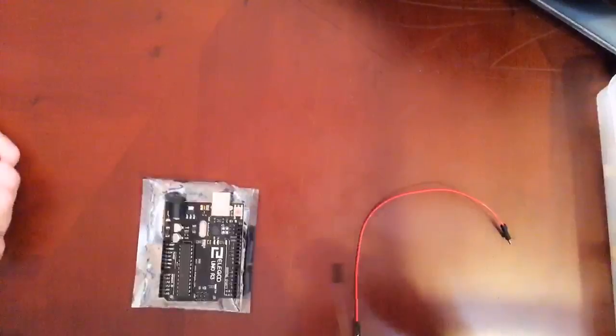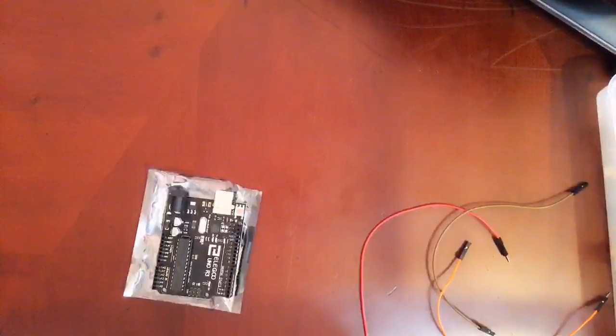The DHT11 digital temperature and humidity sensor is a composite sensor which contains a calibrated digital signal output of the temperature and humidity. The dedicated digital module collection technology and the temperature and humidity sensing technology are applied to ensure that the product has high reliability and excellent long-term stability. The sensor includes a resistive sense of wet components and an NTC temperature measurement device. It connects with a high-performance 8-bit microcontroller.